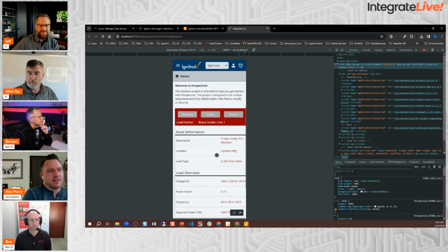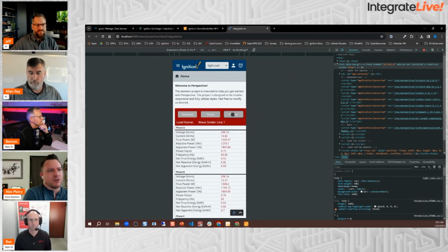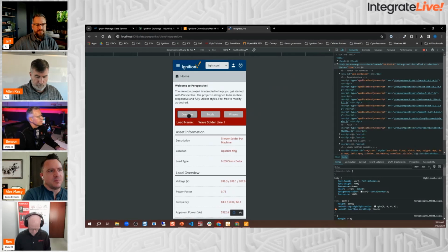Also, if you wanted to add this to your history, you would want to go through the UDT instance or the UDT configuration and set up your tag history and things there. Since we don't know your historical tag provider settings, we didn't populate that to begin with.